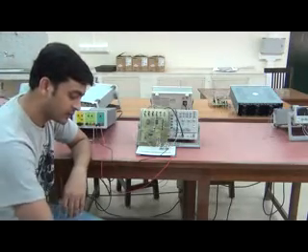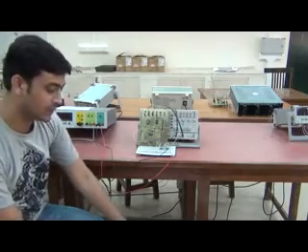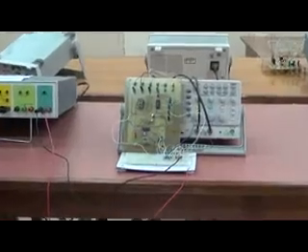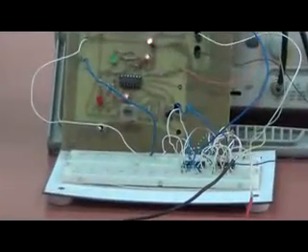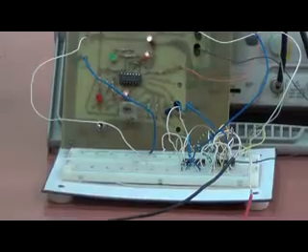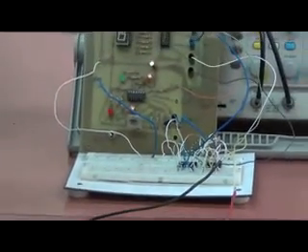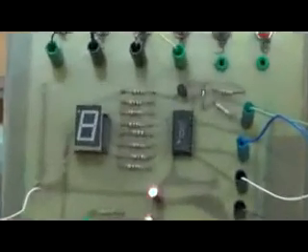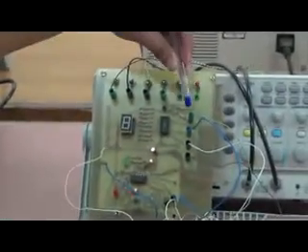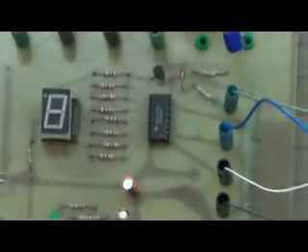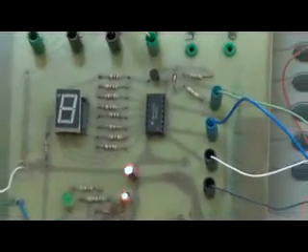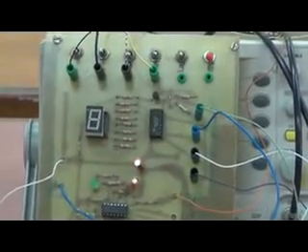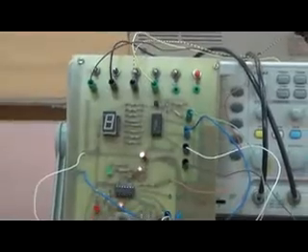Now we have designed the divide by 8 ripple down counter on the breadboard, as can be seen, and will verify the output on the digital test board. Again, the output will be checked using the 7-segment display. Since we require 3 output bits, we have grounded the MSB input to the ground. The rest 3 are used to display the output of the counter, and we'll give the power from the power supply.